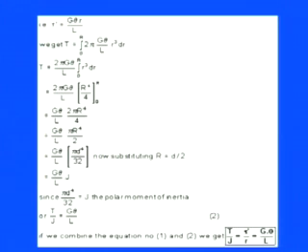So now the variable function is r cube dr under the integration from 0 to r. After integrating, T equals 2 pi G theta by L into r4 by 4. After integration, r cube dr is r4 by 4, and we apply the definite limits from 0 to r. So we have G theta by L into 2 pi r4 by 4, or after cancelling 2, G theta by L into pi r to the power 4 divided by 2.